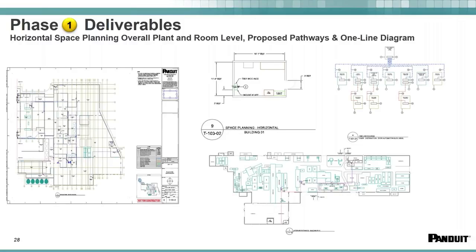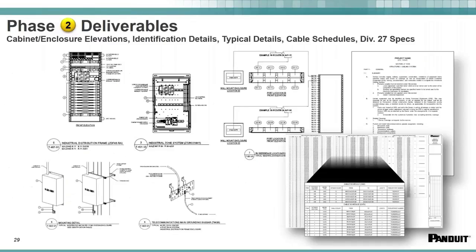So after we've now identified all the devices, all the locations, and basically how we're going to wire them up at a high level, we're now ready to move into the more details. So the details are now going into the switch elevation views. And we'll be showing all the devices and where they're going to be located in the rack, or if it's in an enclosure, we'll show the patch panels and the switch locations, and then get down to the port level.